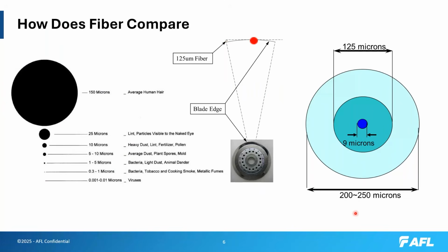The illustration that's popping up, this little section is the fiber's 125 micron cladding as it compares to the fiber optic cleaver, such as a CT50 fiber optic cleaver. You'll see the edge of the blade as it compares to the relative size of the fiber. Keep in mind that the fiber you see sitting on top of that blade is the 125 micron cladding, and we're still trying to align that 9 micron core in that fiber. That's what's carrying the signal that you're trying to minimize loss with.